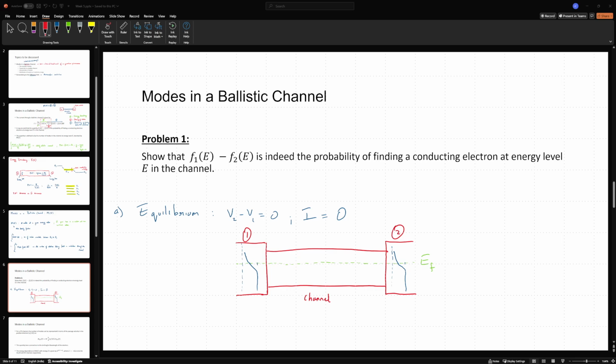And we will also know that the value of the Fermi function, for most reasonable temperatures, is essentially... In fact, if I go to very high temperatures, this is going to be a flat line at half. But even at something like 300 Kelvin, where kBT is a very small value, it is not high enough to populate the entire conduction band, because we know the intrinsic charge carrier concentration in even materials like silicon is going to be something like 10 to the power 10 electrons per centimeter cube, which is actually pretty low. So even at room temperature, silicon is going to behave more or less like an insulator. It is a semiconductor, yes, but it's going to be a semiconductor with a very high resistance.